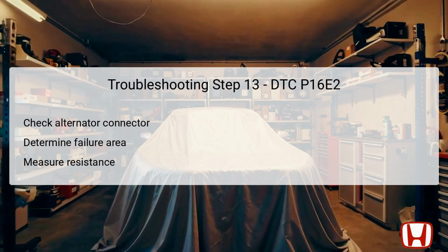Start again with the vehicle in the off mode. Disconnect the alternator's 1P connector for validation, following up to reassess resistance between designated test points. The testing matches previous routines, aiming to gather values associated with body ground conditions. Achieving a result of 1 megaohm or greater will proceed to additional troubleshooting directions, while failing to meet these values will indicate the necessary assessment steps leading directly back toward the alternator.